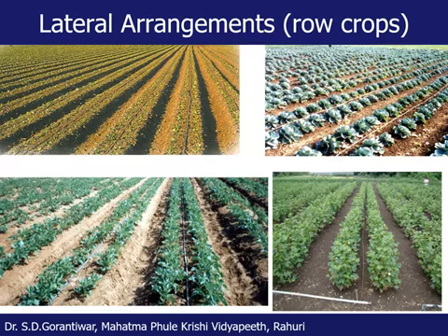for the different kinds of crops. Cabbage is there, cotton is there, and many other crops are there. So this will save us the lateral cost. Okay, so this is also called paired row planting. Earlier I showed banana, where it was only one lateral per row of the banana plantation, and here it is one lateral for 2 rows of the vegetable crop.